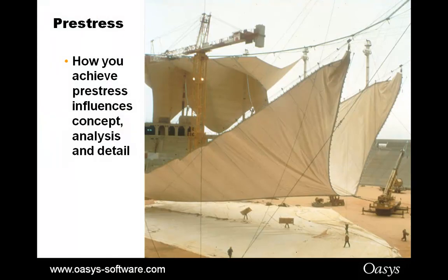Another important output, and also input to the form finding, is the prestress. Now, the prestress is crucial to the form finding, both in terms of the balance of the prestresses, so you're balancing the fabric prestress against the cable edge prestress and so on, and that varies the end result in shape, but also how you achieve the prestress, whether it's through cables, whether it's through solid points and so on. These all make a big difference to the final shape. And quite often with form finding, you are playing with the various prestresses to get the right shape.